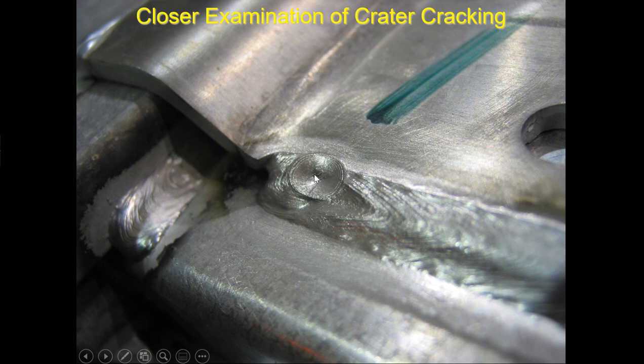Remember that black oxide is formed from the molten aluminum being exposed to oxygen. So when the robot was gone, the gas was gone, and it exposed it just a little bit, because the center is the last part that solidifies. But as it shrank, it didn't have any fill. Like we said, the wire had stopped, and of course it split. These splits come from this weld material shrinking and having no material to feed it, no material to compensate for it, so it pulls itself apart. But a die grinder fix, a little bit of a termination fix on that one, and it is ready to go.